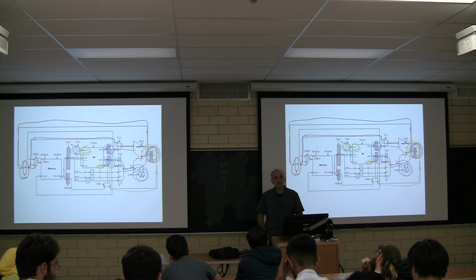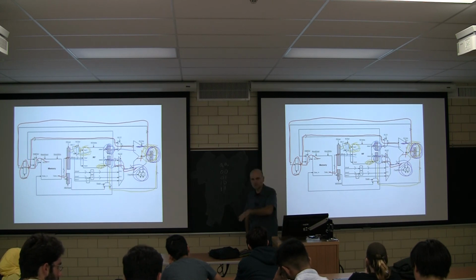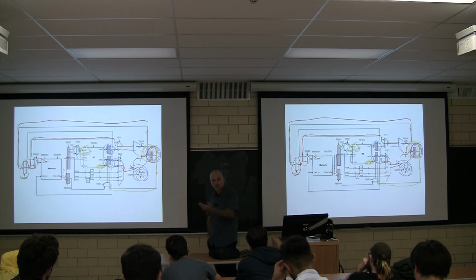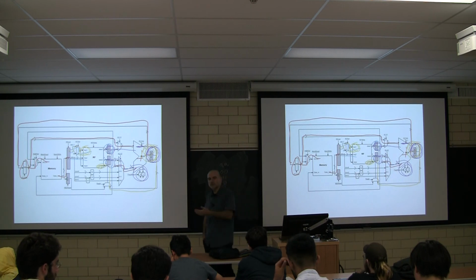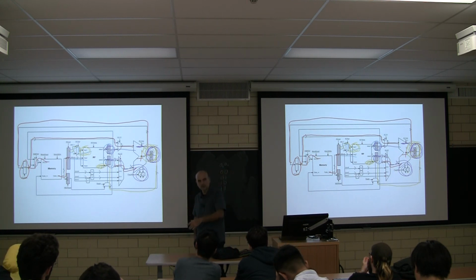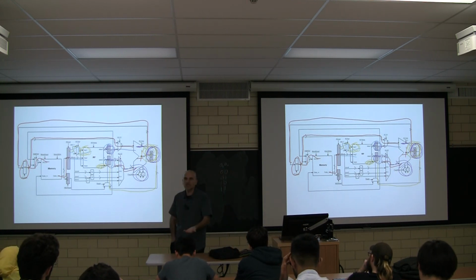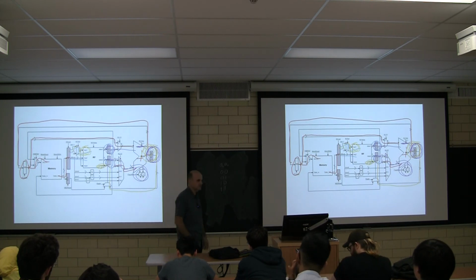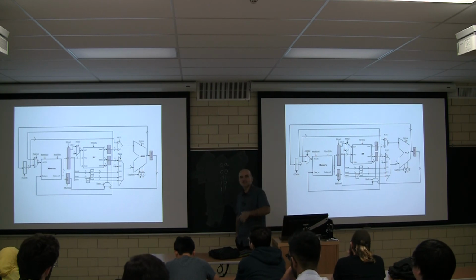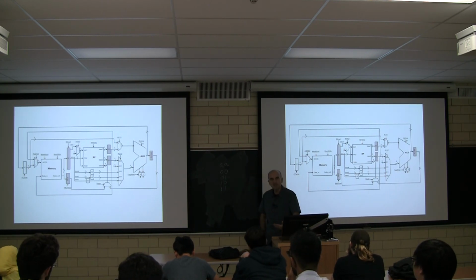Sometimes you're going to be certain what you do is a good thing. First cycle, PC and fetch from memory. You know you need both, period. Sometimes what you do is not going to be necessarily useful. Second cycle, you're looking at the instruction, got to do that, there's no way around it. And how about we read 2 registers just because this may be useful? In the first case, this is not speculation, cycle 1. You're doing useful things no matter what. Second case, you're using concurrency, but it may not be useful, it's speculation. Fair enough? Okay. Let's look at ORI now, and let's understand how decisions at the instruction level design can actually impact our machine underneath.